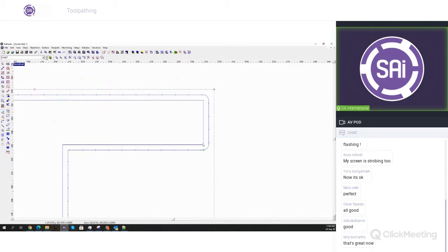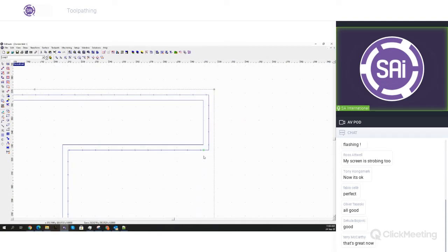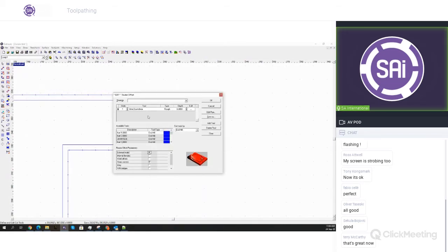But for the smoothness of the movement of the machine, rounded corners are good to use. You can set sharp corners as well. As you'll notice, the movement of the machine is going to be sharp here as well. That makes little difference for the round tools like end mills or ball nose tools. But if you, for example, take a conic tool or an engrave tool,